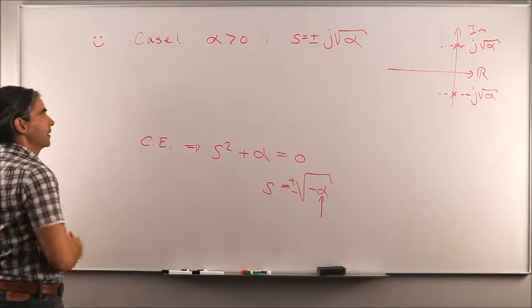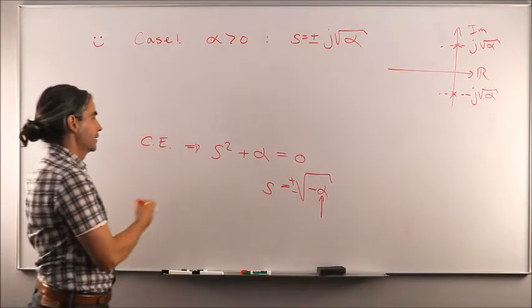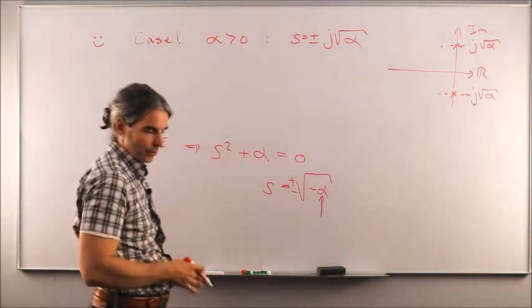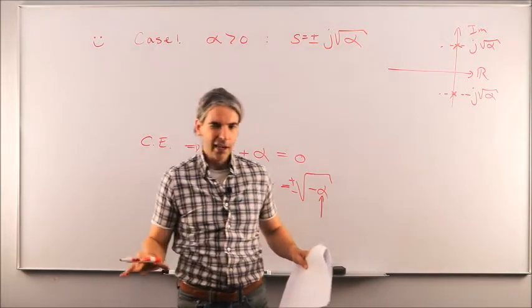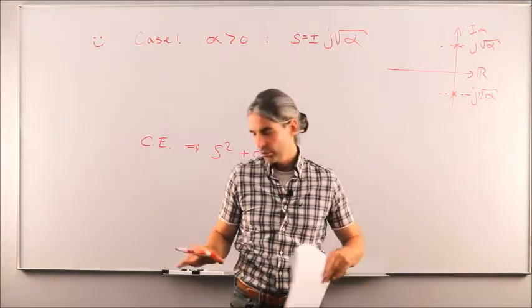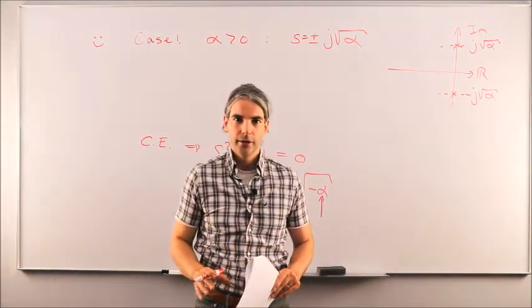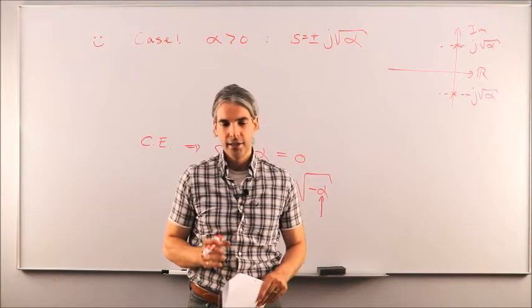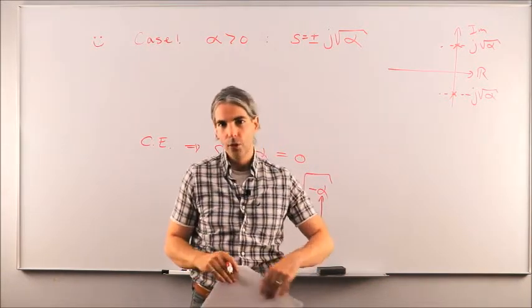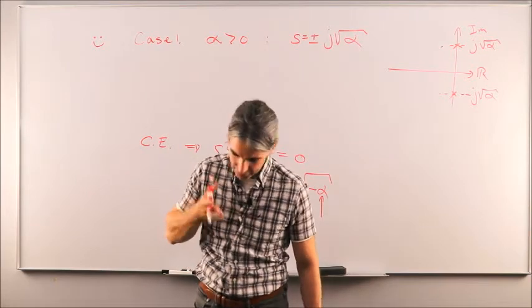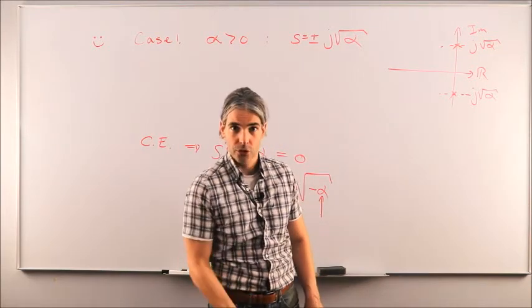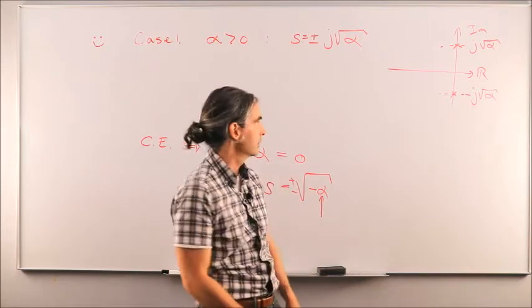Makes you happy, because if alpha is larger than 0, then you get a pitch motion that is stable. So the spacecraft is originally perfectly aligned in terms of its body fixed frame to the roll pitch yaw reference frame. Okay, Bx is aligned with Qx, By along with Qy, and Qz along with Bz, such that the spacecraft has its z unit vector pointing straight down in the nadir configuration.